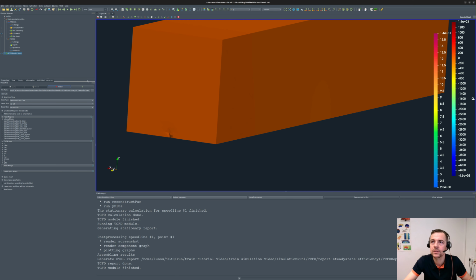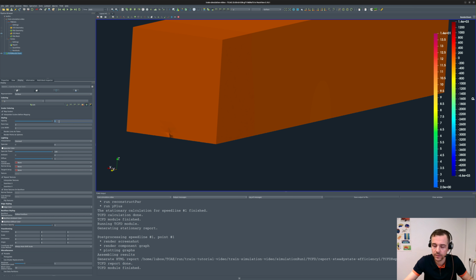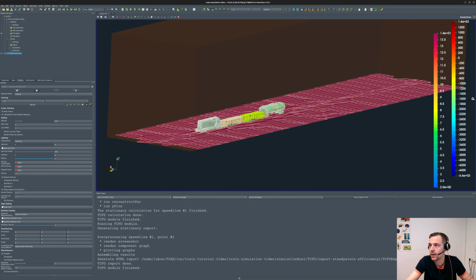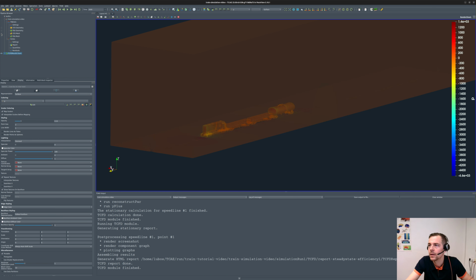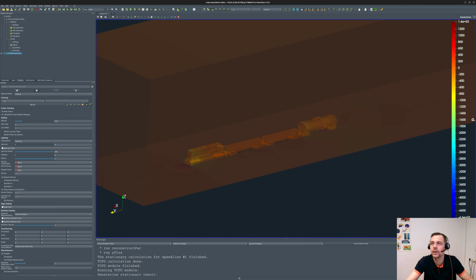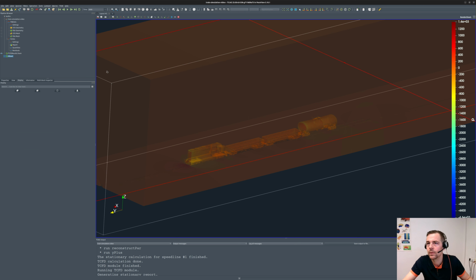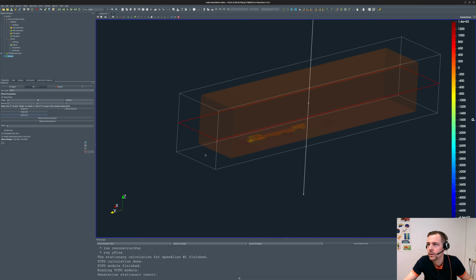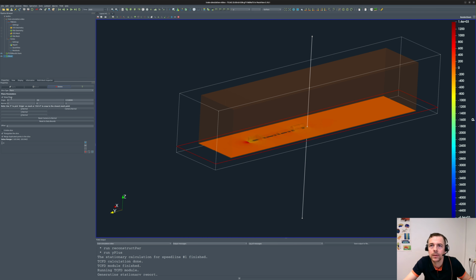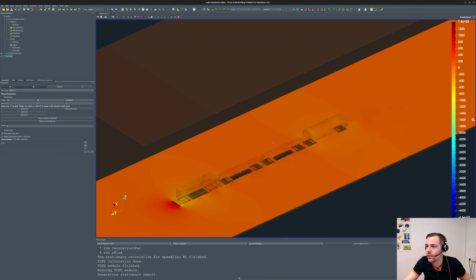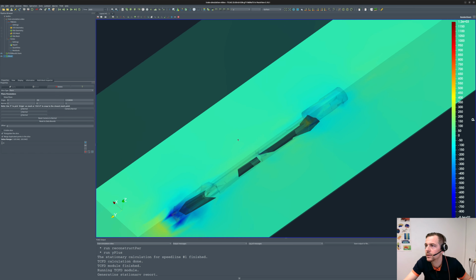Okay, so there is the volume of the virtual tunnel. I will visualize it by changing the transparency, the opacity. Then we can look inside, and what we could do is maybe to show you the simulation mesh in the volume and the pressure results. So I will use a couple of filters. ParaView is a great, really great post-processing tool. So I will use this slice, perhaps this Z normal, and I will pick some random plane where I will be able to show you this plane.